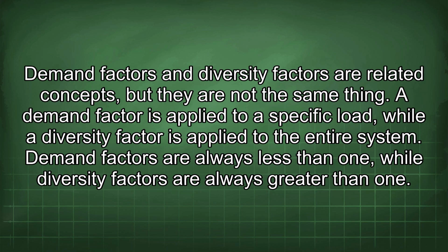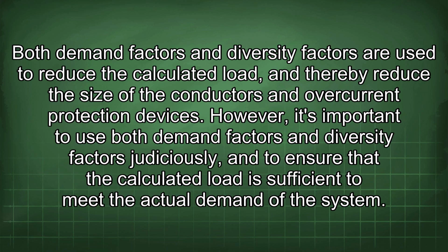Demand factors and diversity factors are related concepts, but they are not the same thing. A demand factor is applied to a specific load, while a diversity factor is applied to the entire system. Demand factors are always less than 1, while diversity factors are always greater than 1. Both are used to reduce the calculated load, and thereby reduce the size of the conductors and overcurrent protection devices.